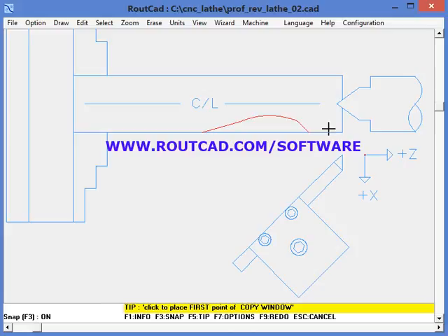Now, what we also have done using line and arc, we have designed the profile that we want to make, out of profile of revolution, out of this 1 inch thick workpiece. And we also have designed a chuck holding tool. Now, what's going to actually happen is we will just give a quick demonstration. We will basically copy this chuck holding tool just to see how the motion will look like.